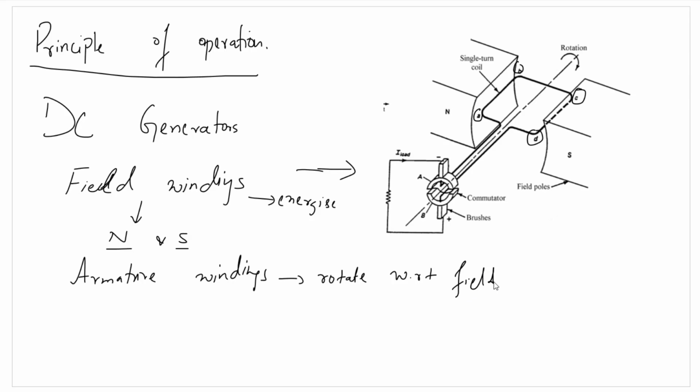In case of induction motors, a rotating magnetic field was produced around the conductors while the conductors were still at standstill. Accordingly, an EMF was induced in the conductors. But in case of DC machines, the magnetic field produced is not rotating in nature. A DC current will not change direction, and the magnitude of the magnetic field will not change.